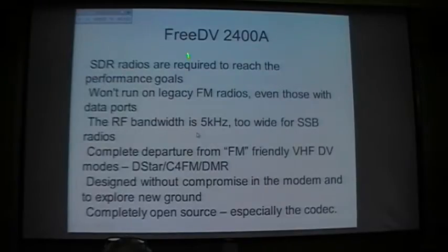The downside, I guess, is it's not going to run on most of your current radios. You need an SDR radio to reach the performance goals. In particular, it won't run on legacy FM radios, even those with data ports. The other way to do this is to use an SSB radio and move your signal up and down to RF using an SSB radio connected to a PC. Can't do that because it's too wide for SSB radios. We need the full 5 kilohertz.